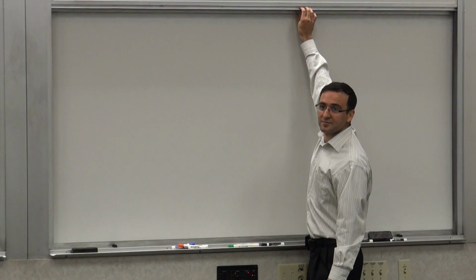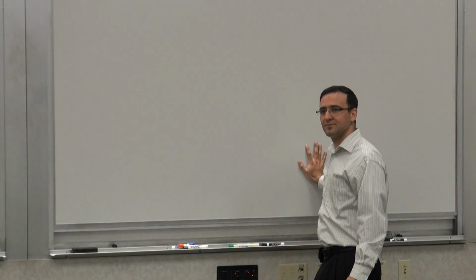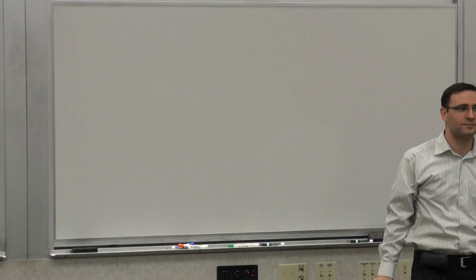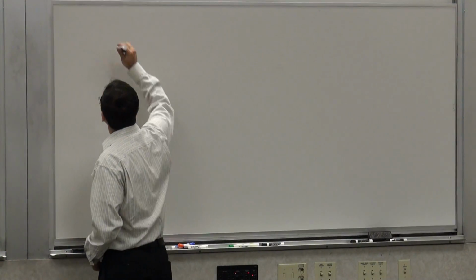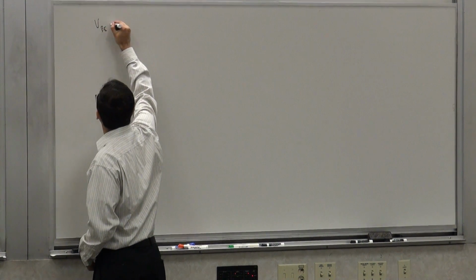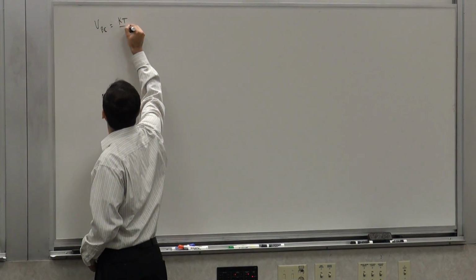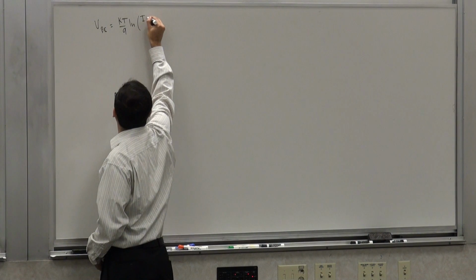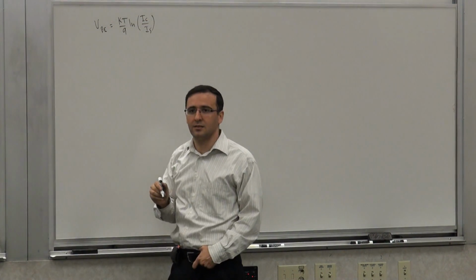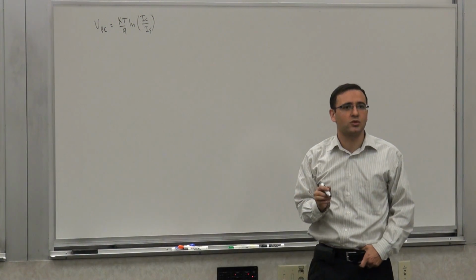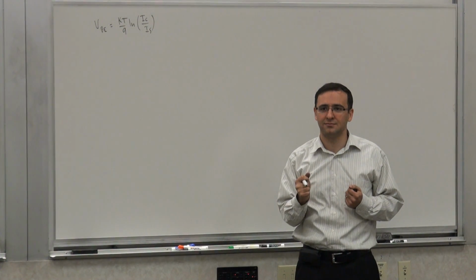So, how do we make that? Where do you see a VT? Not the actual voltage, I mean, which expressions do you see VT in? The collector current thing, or like VBE, the expression that we have, right? So VBE itself had a KT over Q. It's VT ln of IC over IS. The problem was this IS. That messed it up. So somehow I have to eliminate IS.